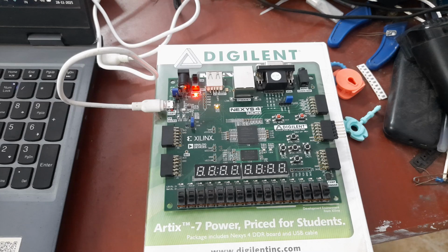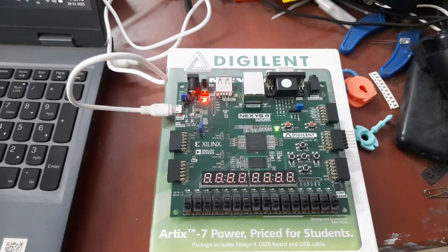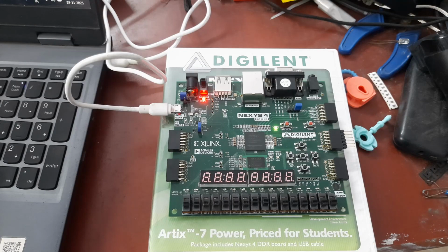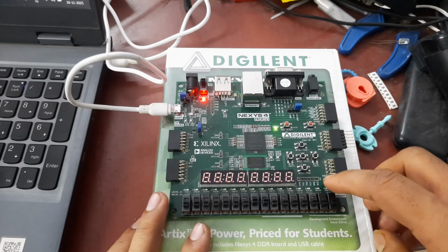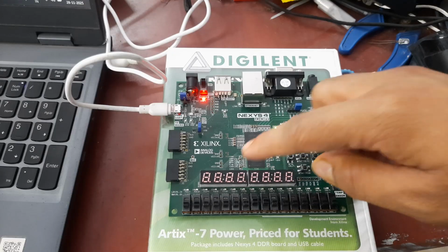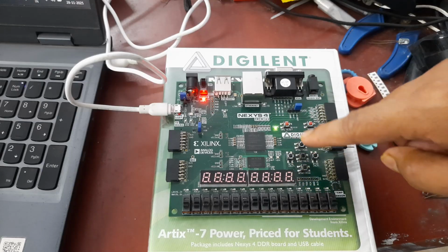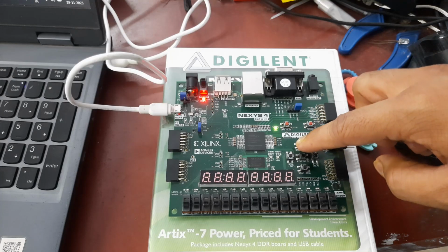Let's just see what is going to happen, and I will explain while I am testing everything. So let's see the implementation. First off, I will upload the T flip-flop code and I'll show you what is going to happen, because I have one interesting thing to show you. So on the constraints I have set up this pin, which is M18. If I find M18, this one is the pin which is the toggle pin. So you can imagine the square wave running, and once I press this, the output will start toggling. One of these LEDs should toggle. So let's see what happens when I push this.